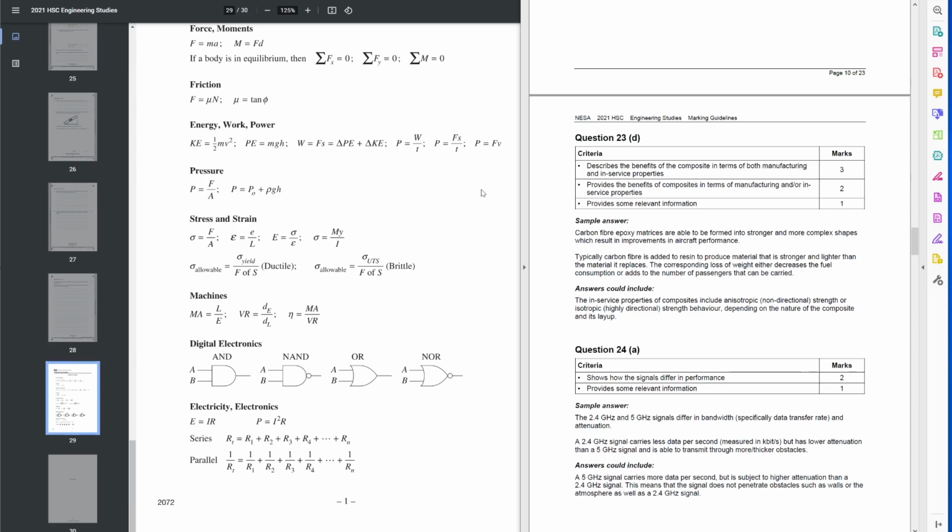There's a big difference between the strength of timber when we run along the grains versus going transverse to the grains. And this is why plywood is a lot stronger than a sheet of timber, like a timber board. The reason for that is because plywood has bidirectional strength. Every layer of the plywood goes in an opposite direction, which means it has a two-dimensional isotropic strength. It's still not three-dimensional. If you get thick enough material of carbon fiber, you can weave it in such a way that it's strong in all directions. But typically, when we're using carbon fiber sheets, we're going to get bidirectional strength.